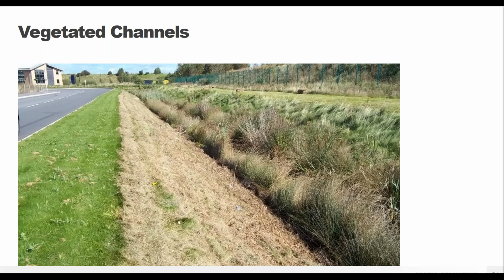And so even with that liner, vegetation can still grow because you're holding that 6 inches of topsoil within the GEOWEB panels. So now when stormwater overflow causes the channel to become flooded, the side slopes are still going to be protected. The channel can do its job of conveying that stormwater wherever it needs to go.